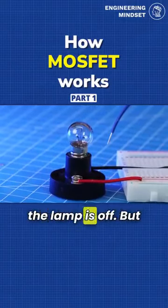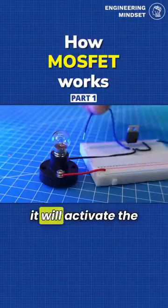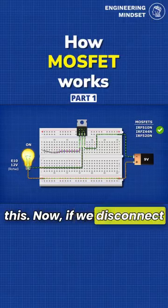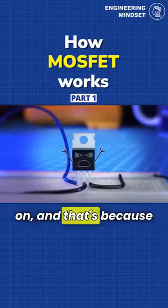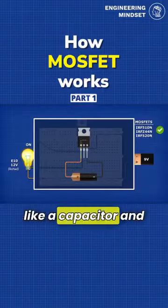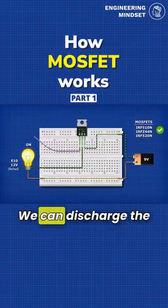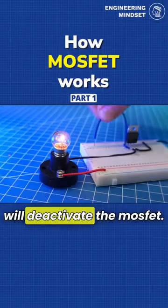Notice that the lamp is off, but if we connect the gate wire to the 9-volt supply, it will activate the MOSFET and the lamp turns on. Current is flowing through the circuit like this. Now, if we disconnect the voltage to the gate pin, the lamp remains on, and that's because the MOSFET is now stuck. The gate terminal acts like a capacitor and it stores charge. If this charge has nowhere to go, then the MOSFET will remain activated. We can discharge the terminal by providing an exit to ground, which will deactivate the MOSFET.